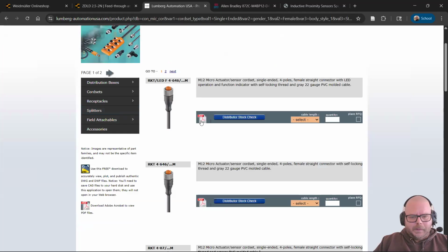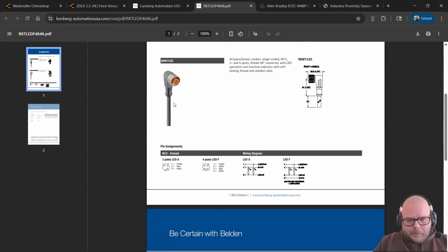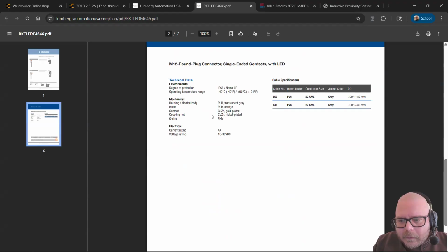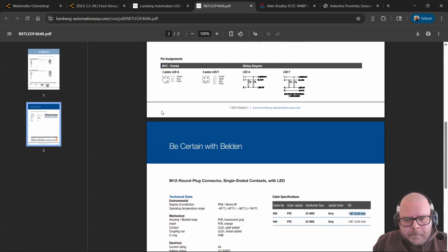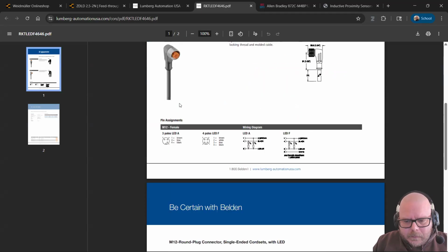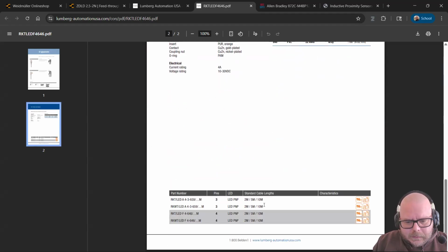probably even deeper. Like we can get to the PDF, and this should be more details for this cable. So the individual wire gauge, does it tell me what it is? Gives me the OD of the cable, which we will need. Individual conductors, does it tell me? They are probably going to be something like 18 gauge. Maybe even smaller, 20. Yeah, but here's the available length. So 2510, we can get it in.